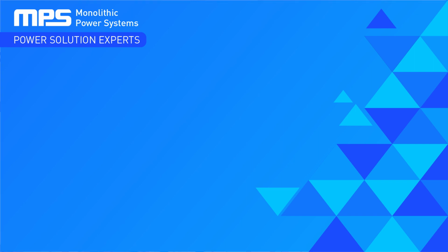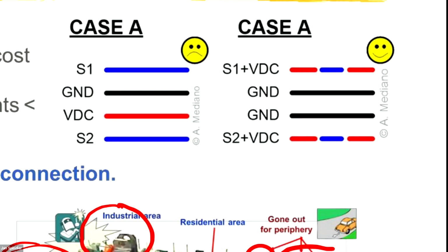The easier answer for this is you can look at the data sheets of converters like MPS, and you will have a lot of information about how to place these elements. Usually it is to separate from the switching node, to make the switching node as small as possible, and perhaps, if possible, to put this on a different side of the PCB. So there are different techniques you can apply.